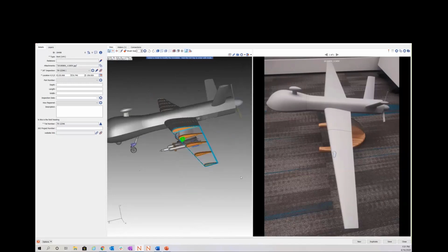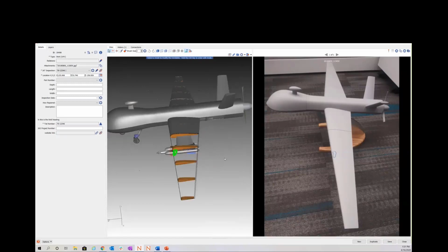Another thing, it will only map to the surface of the rib. It doesn't have a depth feature to it. Right. Let's say you have a dent or something that propagates down into your model, you would have to create another field to capture depth information and say, hey, this dent goes down or this gouge goes down a 10th of an inch or 20th of an inch.